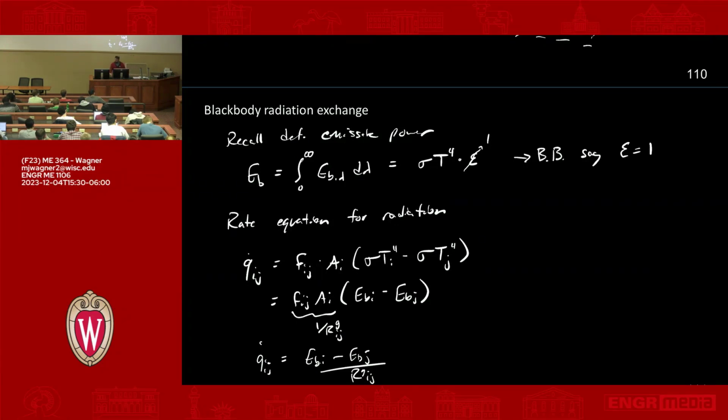And to maybe give a picture to what we're saying here, we have some surface up here. Let's call this surface I. And we have another surface over here. This is surface J. And what I'm saying is that for heat to flow from I to J, there's a resistance in between these. This resistance we call our RGij, a geometric resistance. Units are 1 over meter squared.